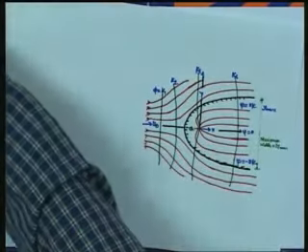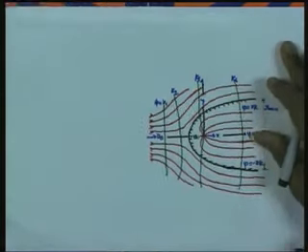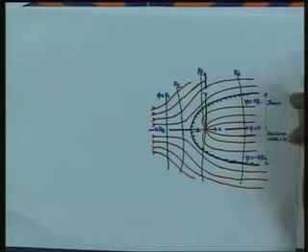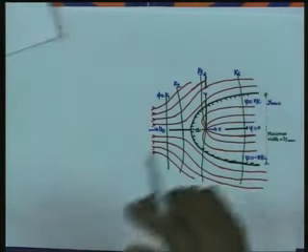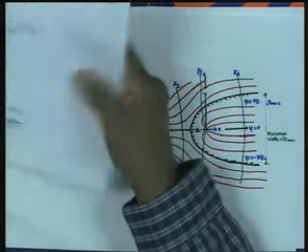So with respect to this figure, for this particular problem, the half body is obtained by superposition of a source and a uniform flow, and then we calculate the stagnation points and also the maximum thickness of the resulting half body. So like this, we have now seen 2 examples: one is superposition of a vortex and a source, and another is superposition of a uniform flow and a source, so that we got the half body.